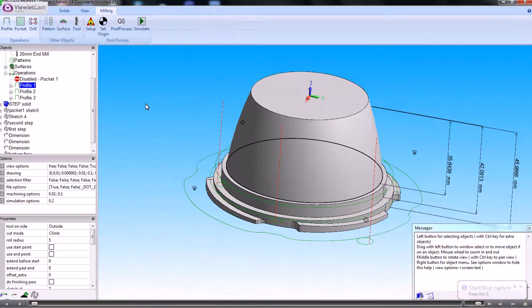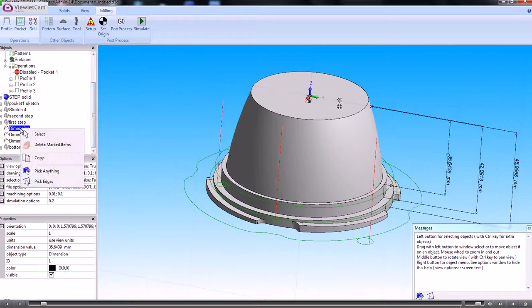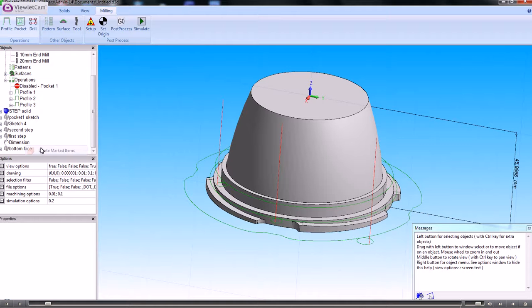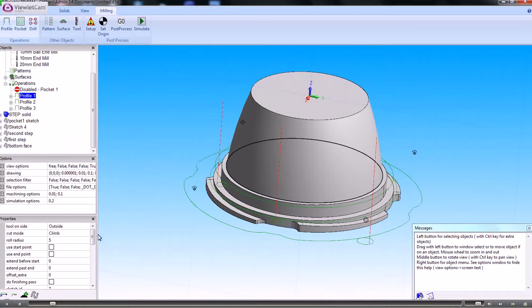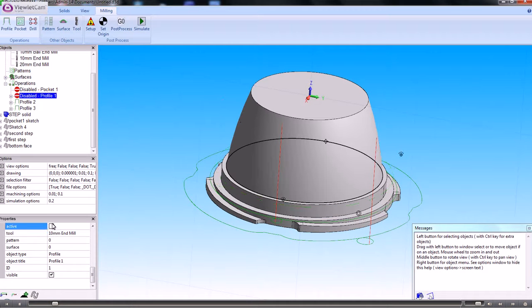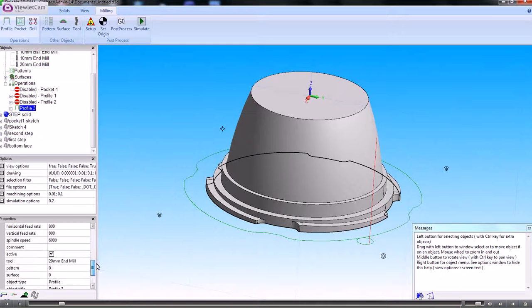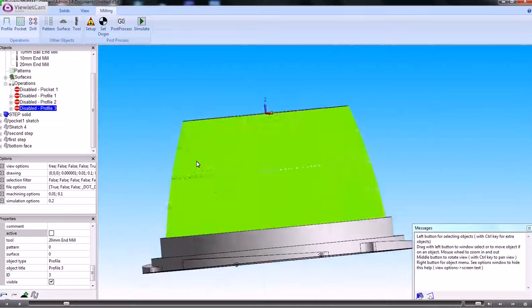In this video we'll just show you how we can machine the sloping faces. So just for clarity, I'll go in and delete those items by right clicking on the dimension, because I no longer need those, and the profile operations, then I can just make it non-active, and therefore the graphics will be that much clearer. Okay, so machining those